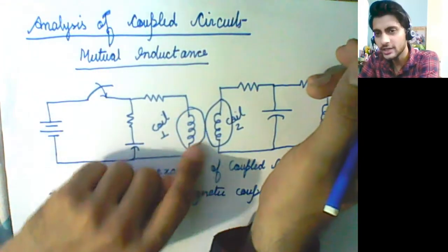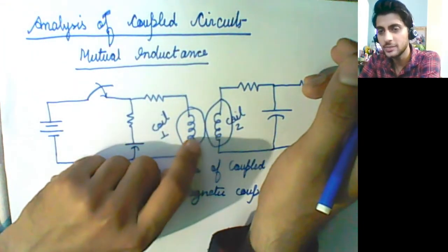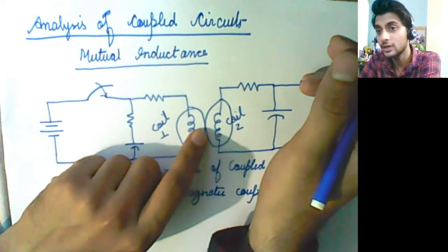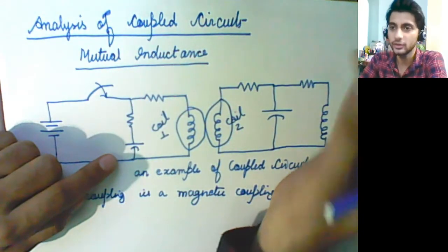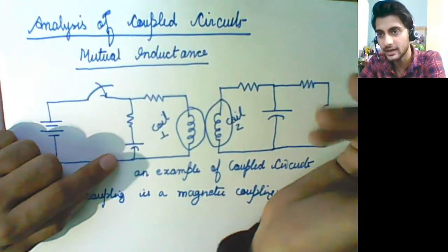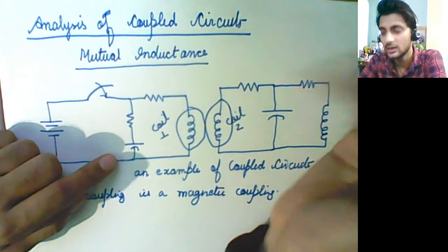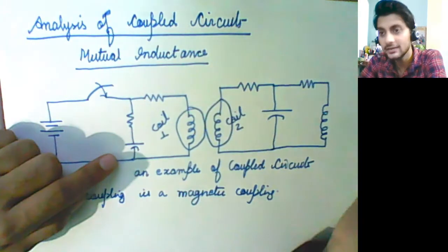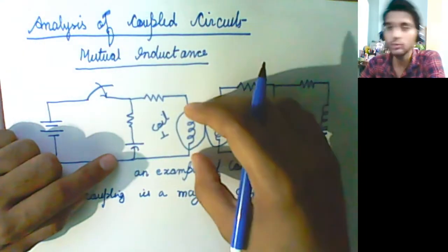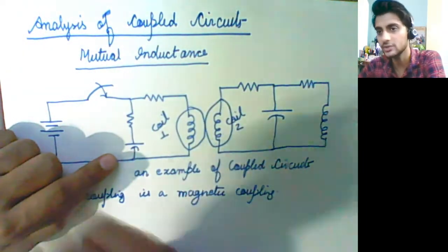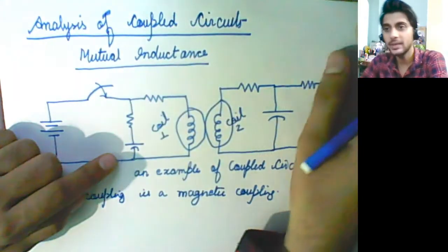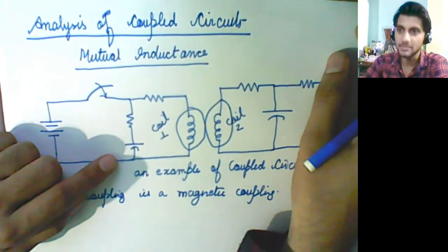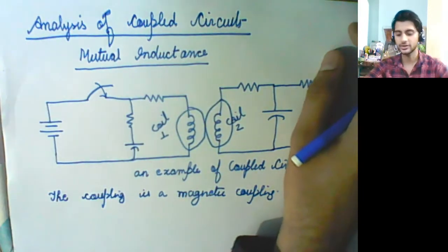You see that the voltage across this particular inductor will be affected only and only if there will be transients. Otherwise, I have already told you that an inductor is nothing but a wire, and for DC conditions the voltage across an ideal wire should be zero, and the same should be true for a coil also, because a coil is nothing but a geometrically modified wire, modified in such a way that magnetic fields are induced or flux is induced across this.